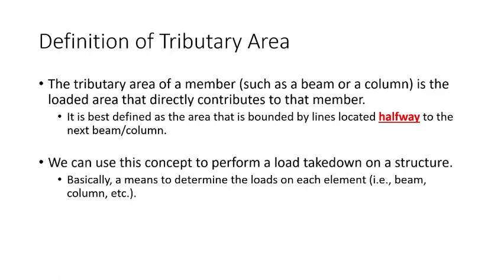The other place you'll see two-way slabs is whenever you have a really heavy load on the floor. Drinko has some two-way slabs because the second and third floors have book stacks. Book stacks are really heavily loaded. They have a waffle slab system in there that acts as a two-way slab.